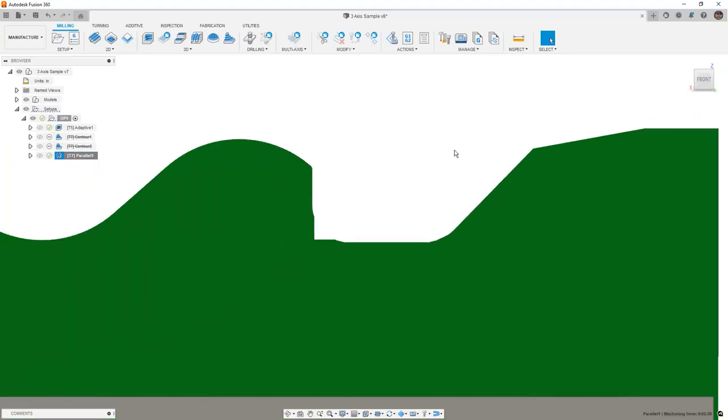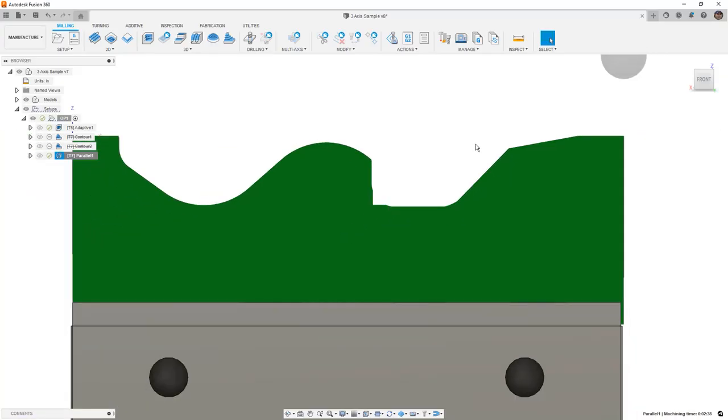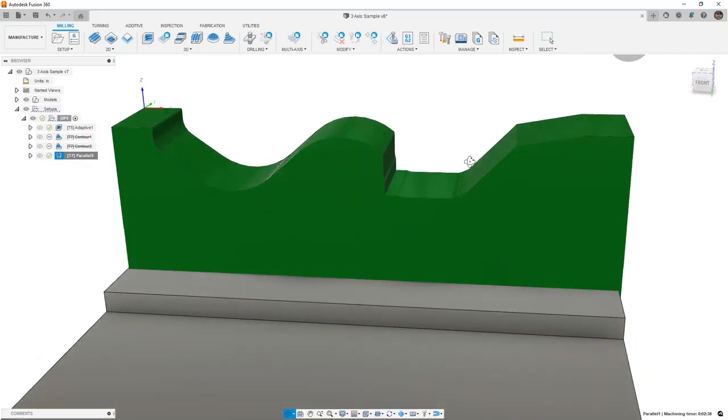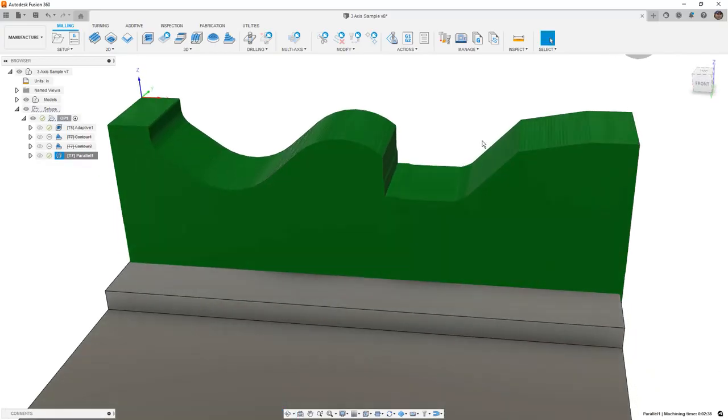But once again, Fusion 360 does allow us the option to drive these toolpaths based on a cusp height or a step over value. The best thing to think about is whether or not toolpaths like these can apply to an entire part, or if we should restrict them to certain angled faces or certain areas. Because we've seen that the cusp height and the step over amounts can vary based on the angle of the face, it's often a good idea to focus your attention on certain areas.